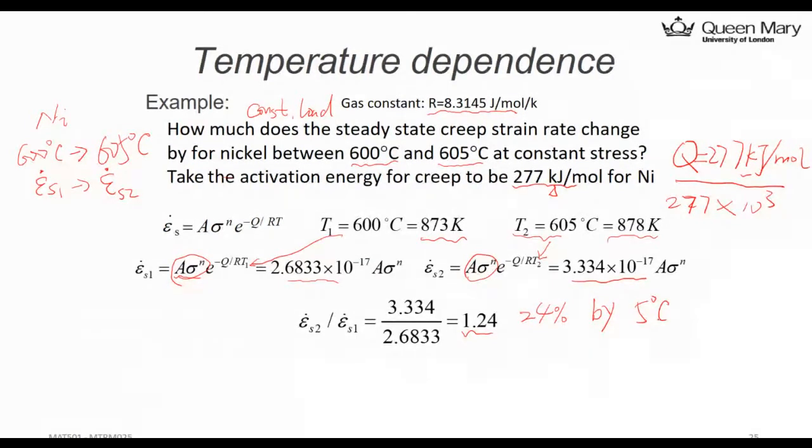You can see that's a very sensitive result. So you can imagine for a creep test and the furnace, normally the furnace like your oven, you heat up the things. The oven with a fan normally will reach a steady state temperature, but if you didn't control it very well, it will have 5 degree variation, so that you will have a different creep strain rate.